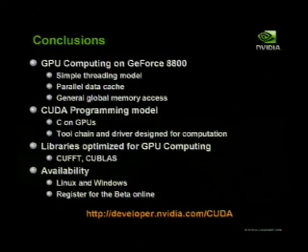So to conclude, I guess I'm getting close on time. I've talked about GPU computing on the 8800. We've basically added a simple multi-threading model to the GPUs with a parallel data cache and global memory access. The software tool chain basically is C on GPUs with a couple of extensions for dealing with the fact that you have lots of threads in the machine, but it's effectively C. Our front end is a fully licensed C and C++ front end, so we're fully compatible, even bug compatible with GCC and Microsoft.